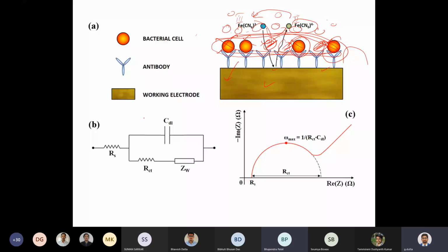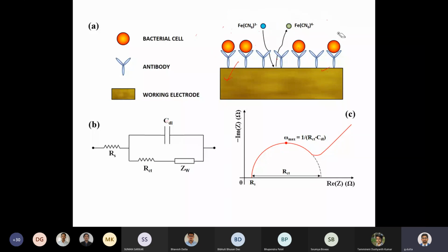Sir, our purpose is to generate high impedance? No, our purpose is to make a correlation between the impedance and protein concentration. So our purpose is to make a calibration. On the y-axis, we will put the impedance, on the x-axis concentration. Now increase the concentration, get impedance.